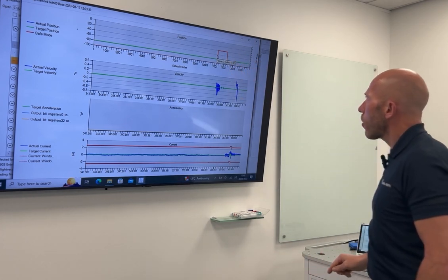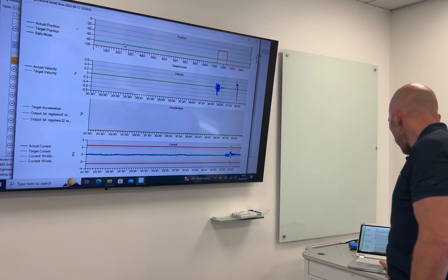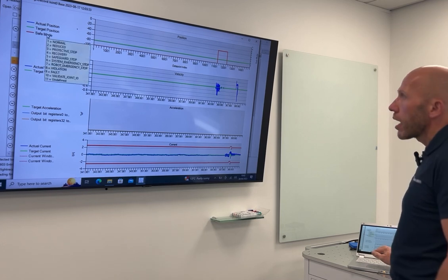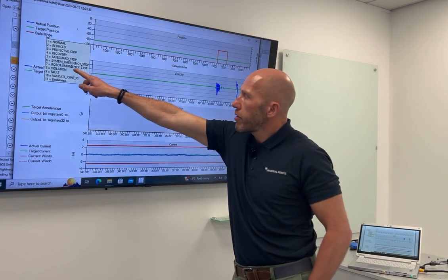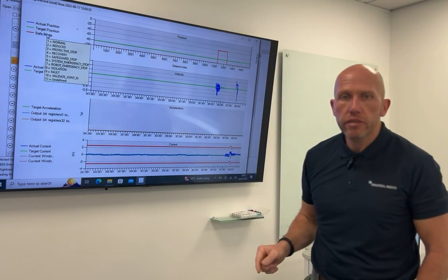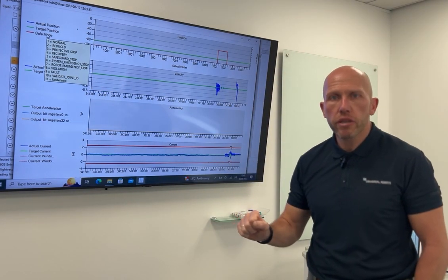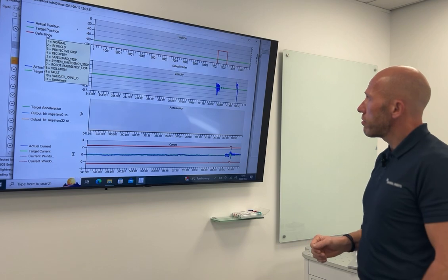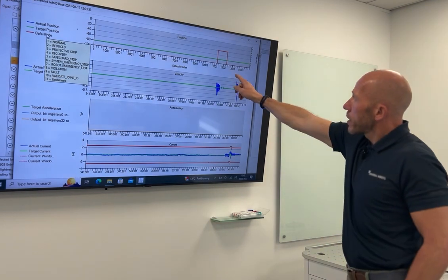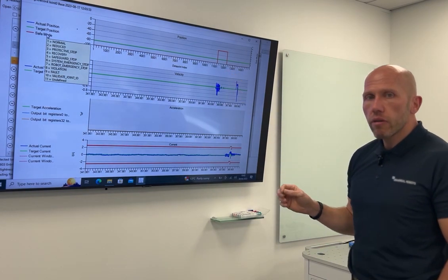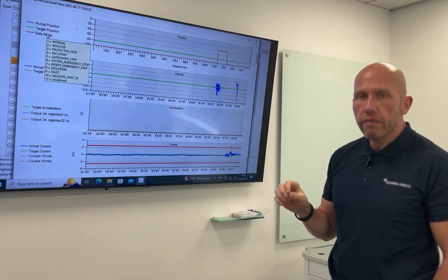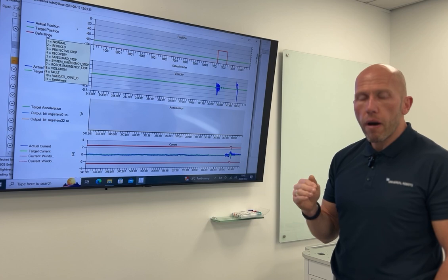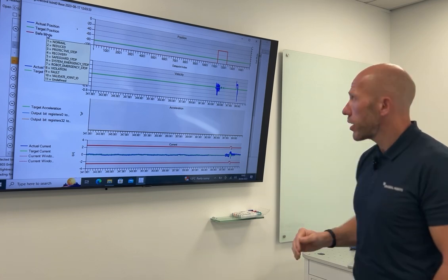So if you wanted to know what that was, we can move over to our safe mode. And here we can see that error number 7 is a system emergency stop. So essentially the robot was emergency stopped, so there's nothing to really concern ourselves here. We can see the script line number. So if we wanted to interrogate the log file further, we could actually look at the script line and find out what part of polyscope the error was occurring.